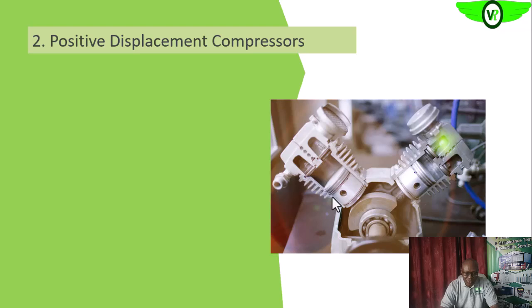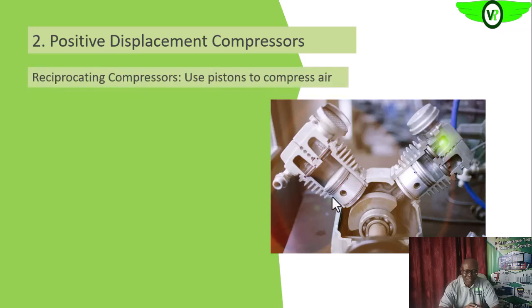So we'll now move to the positive displacement compressors. Unlike the centrifugal compressors or the dynamic compressors, both the centrifugal and axial, what it does is that it reduces the volume of the gas, thereby increasing its pressure. With that pressure and increased stored energy, the gas can travel some distance within your facility.